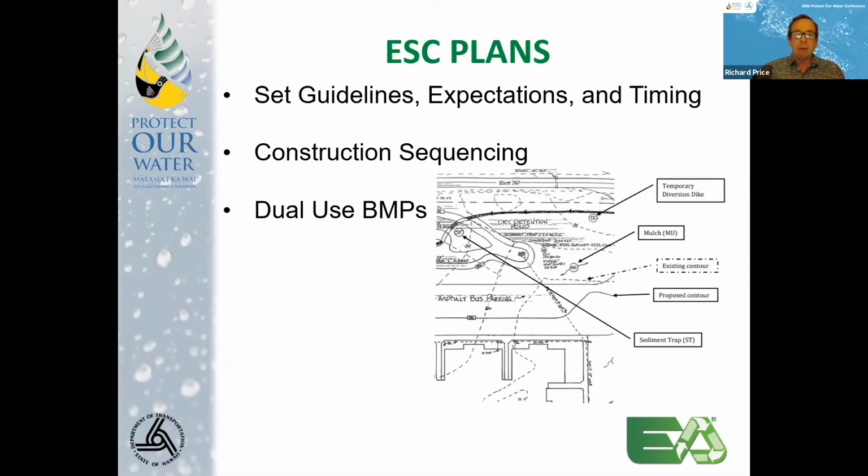A lot of designers are laying out sites now, if they are putting in a permanent best management practice, such as a rain garden or a pond or a detention basin, they will try and route all of the construction stormwater to that location, and initially build a sediment trap or a sediment basin that will allow you to use that location and that footprint for sediment control during construction, and then wait until the end of the project to convert that sediment basin to a pond or an infiltration BMP like a rain garden.